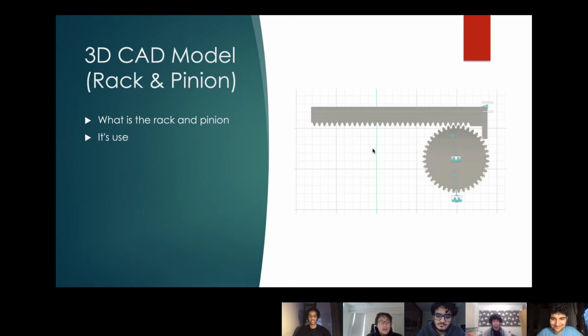We use the rack and pinion system in order to stop the vehicle at the initial position. The rack will go in the opposite direction as the car moves. When the car returns to the datum position, the stopper at the back of the rack will stick the rack and the gear together and stop the rack from moving forward, which will also stop the motion of the vehicle.